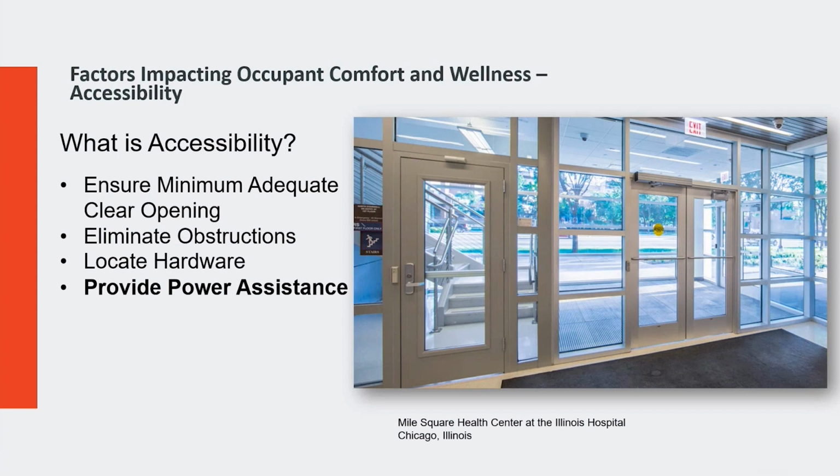Power assist on entrances is also called out. These must be activated by a simple push to open the door and hold it open long enough for someone with a walker to get through. Then return the door to a closed position and hold it there against wind pressure and stack pressure.